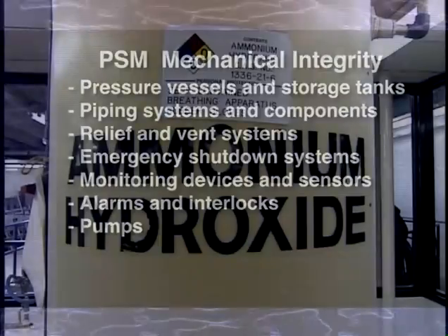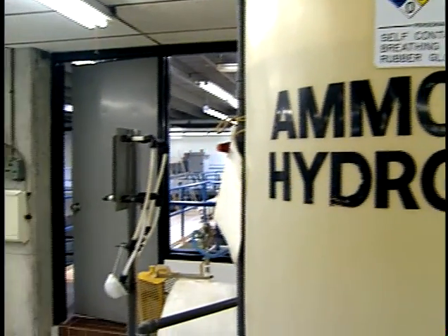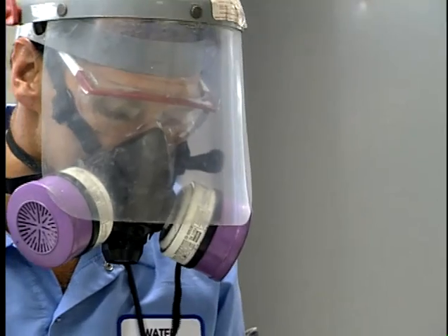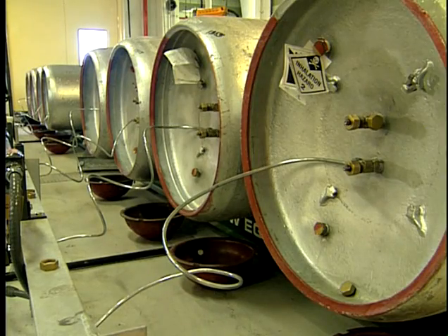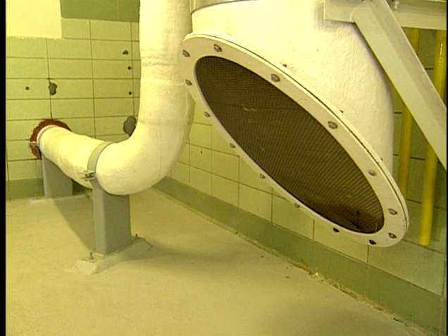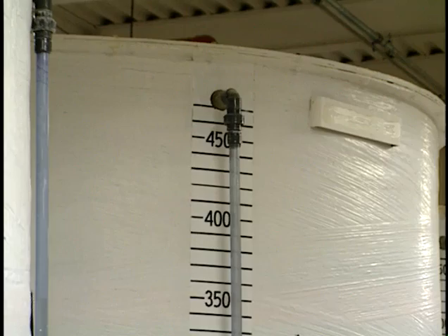and pumps. The first line of defense a utility has available is to operate and maintain the process as designed and to keep the chemicals contained. This is backed up by the next line of defense, which is controlled release of chemicals through venting to scrubbers or flares or to surge or overflow tanks which are designed to receive such chemicals.